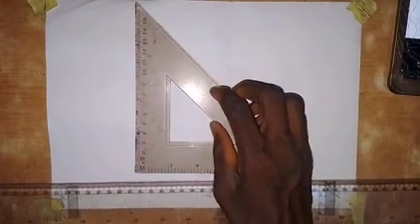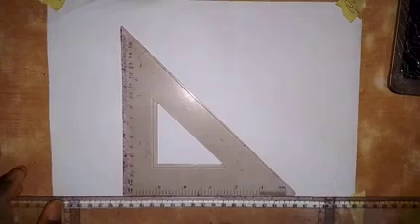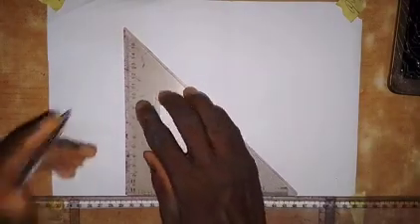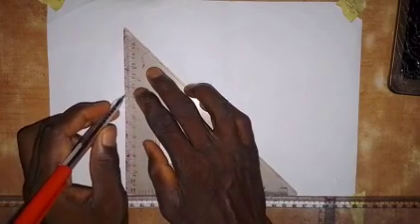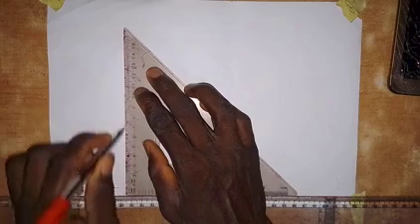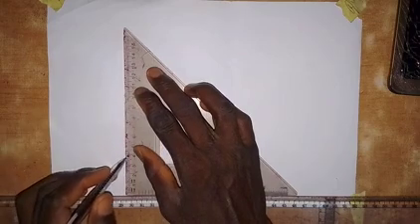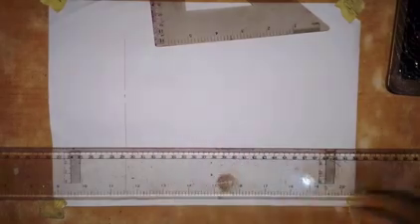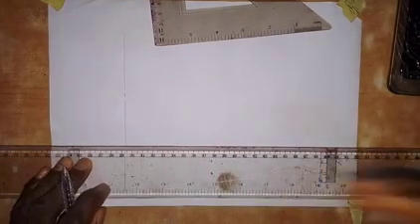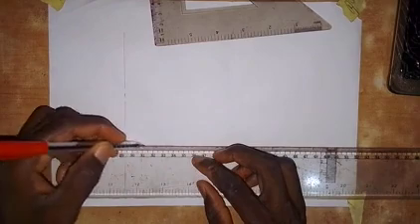The first thing that we are going to do is to draw a vertical center line. Vertical center lines are drawn with a thin long chain line. Always make it a thin long chain line. Then we also have the horizontal center line.